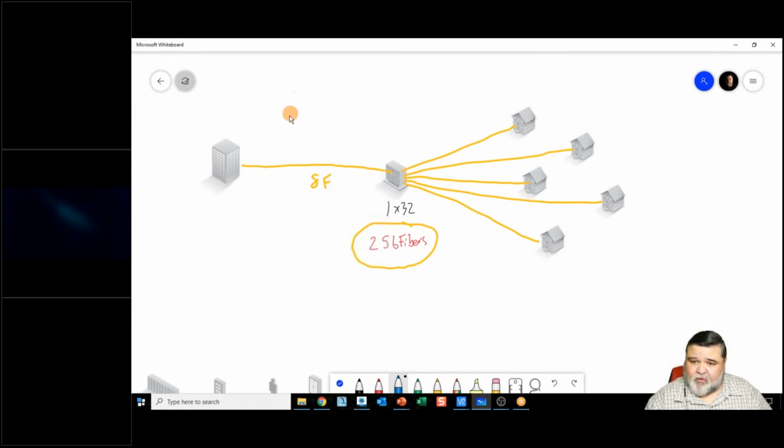If you look at the traditional GPON network that we have available, or even EPON, it's 1490 nanometers downstream, and it's roughly 1.4 gigabits or 2.4 gigabits, depending on which direction you're going. And then you have XGS-PON, which is basically 10 gig PON synchronous, going downstream at 1577 or in that range.